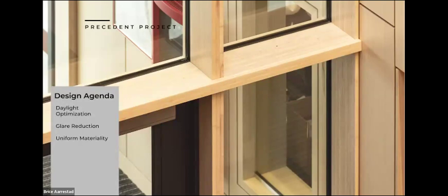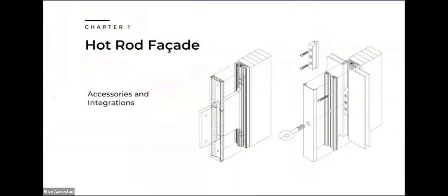Some other components on the hot rod facade that are unique to a timber curtain wall are some of these accessories and integrations. Using a knife plate that would penetrate through the glazing assembly and connect into the glulam timber minimizes a lot of the thermal bridging that occurs with some of these connections, and allows you to do other things on the exterior, which could be sunshades, PV panels, canopies, things like that. Either through these knife plates or through sockets and hooks and different attachment pieces that can be integrated.